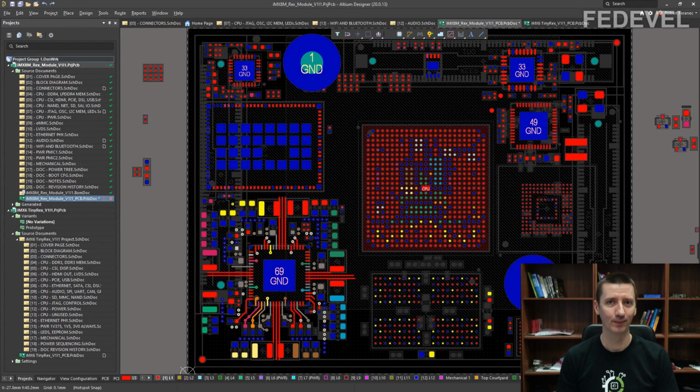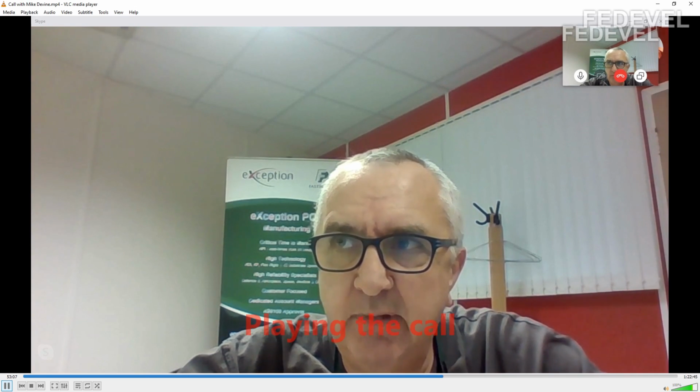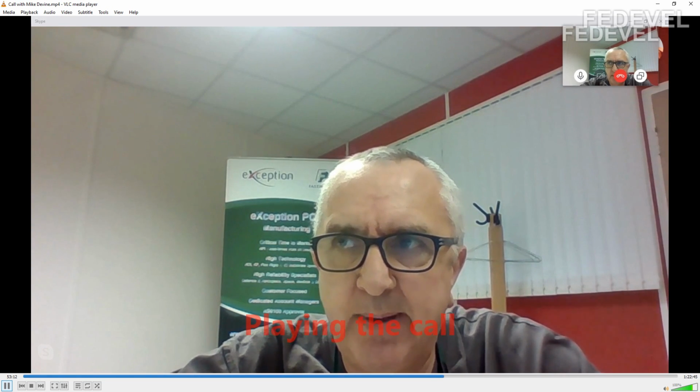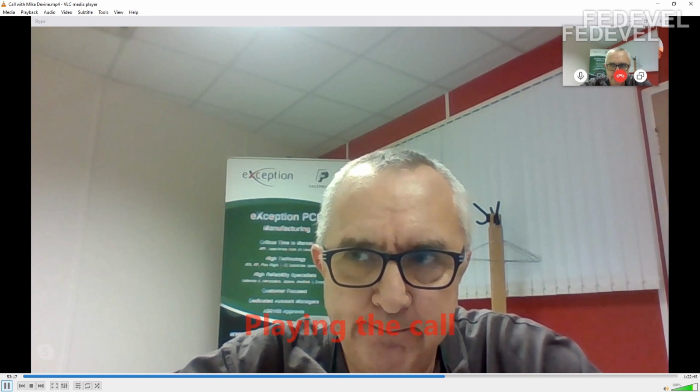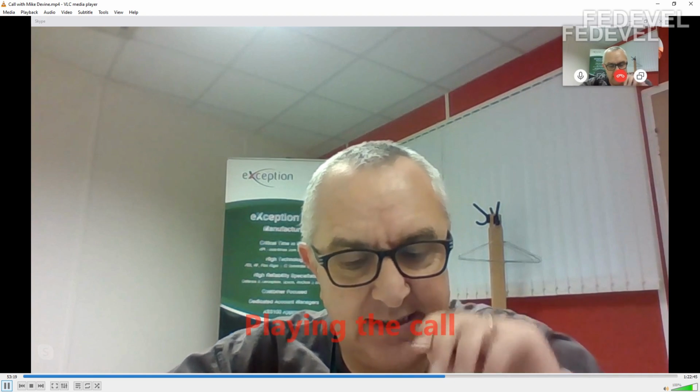And now, the most important question. How much is it going to cost? How much more expensive will my PCB be when I use these resin filled or copper filled vias in pad? Here is the answer. You're probably looking for, if it was resin filled, probably about a 30% cost more. Copper filled, maybe 60% more. Okay, that's quite a lot actually.